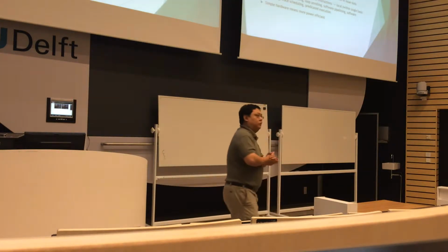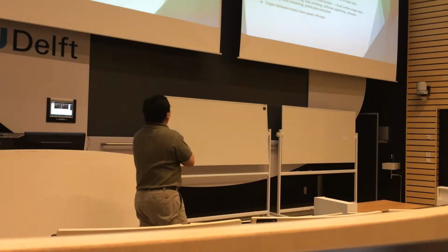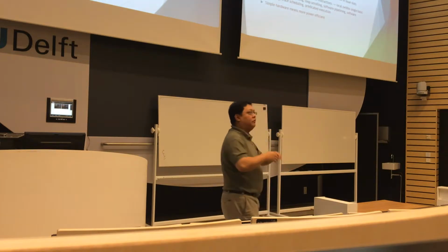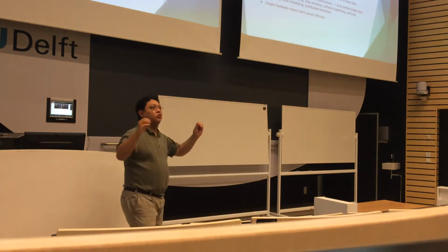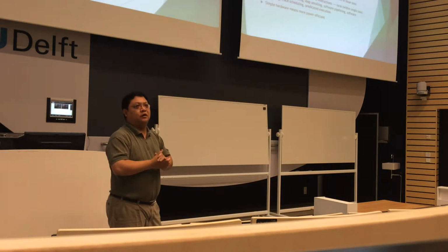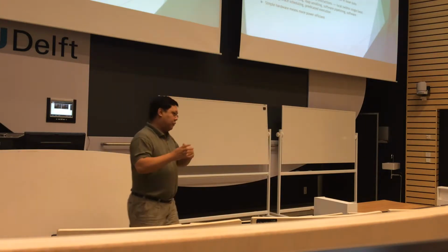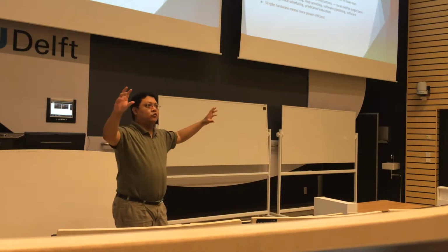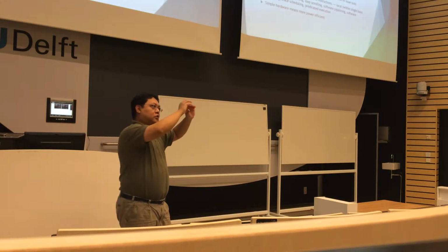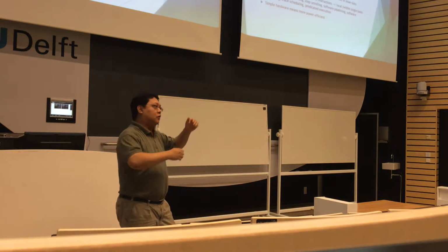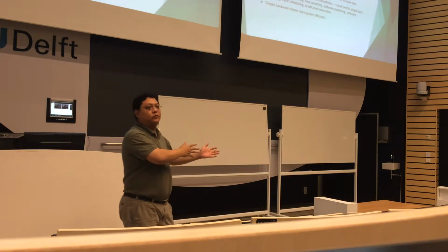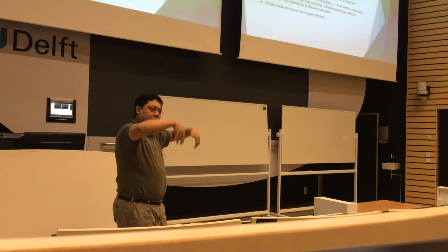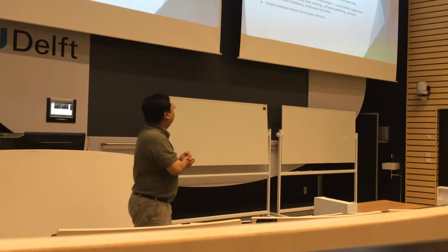So what we do in VLIW processors is that we have a lot of parallel execution units, and you have to specify in your instruction word what you would like to do in parallel. Basically you design a processor that fetches these long instruction words, and you make sure that each slot in your instruction word corresponds to a single data path inside your processor. So then you can go directly down from the instruction to your execution data paths.